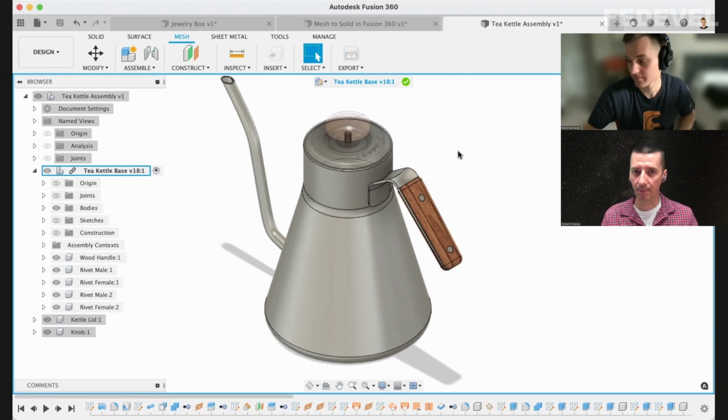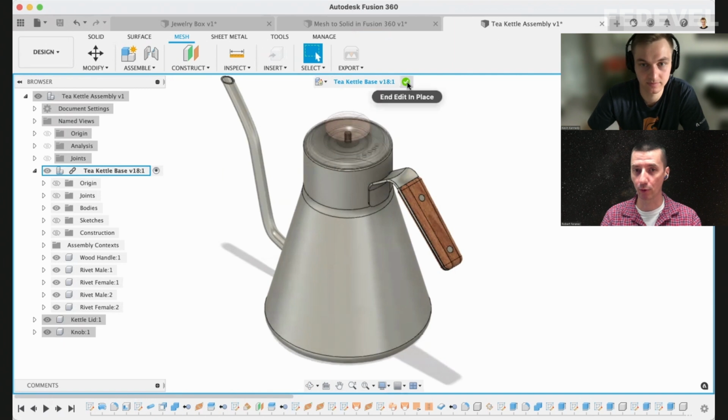So basically, in the beginning, you only specify the parameters that you maybe will need to change later, and everything else that you are designing around needs to be some kind of reference back to these original parameters which you manually specified and which you may change in future, and then everything else will need to adjust because they are referencing.